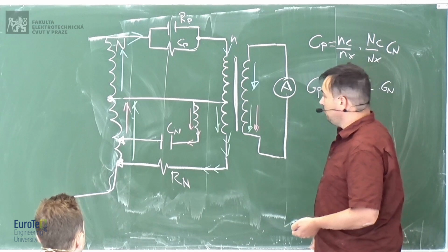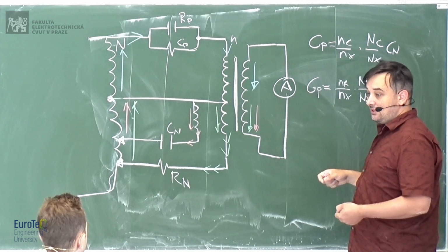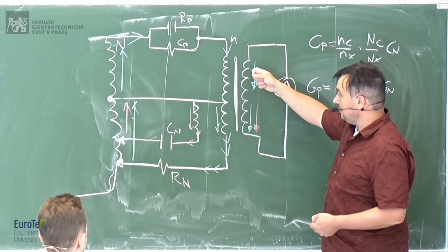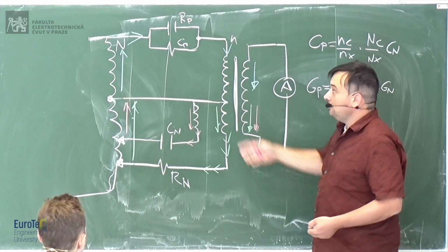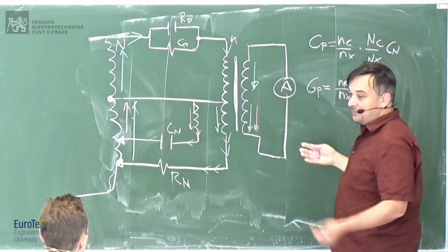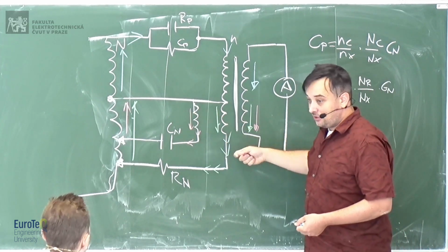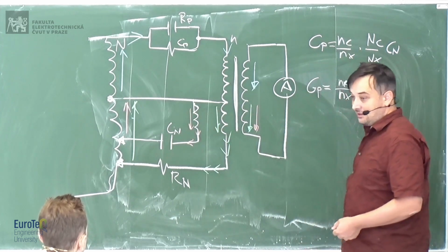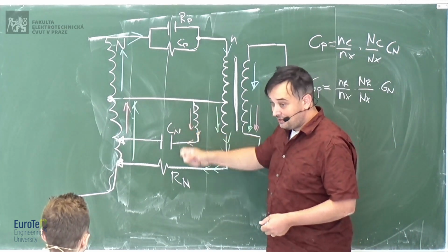So what you do is to, again, check when the ammeter gives 0. When the ammeter gives 0, it means that this real and imaginary part are cancelling the real and imaginary part of the unknown impedance. So you don't know which is the current here. It will have some real and imaginary part. So if you want to null this current, you need a real and imaginary component of the current. So you need some capacitance and some resistance. Okay?